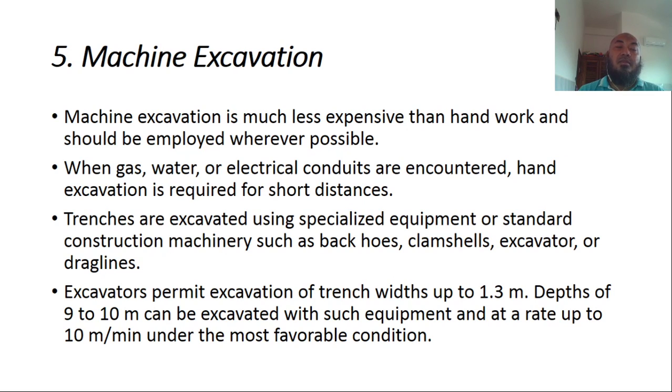Machine excavation is much less expensive than handwork and should be employed wherever possible. When gas, water, or electrical conduits are encountered, hand excavation is required for short distances.